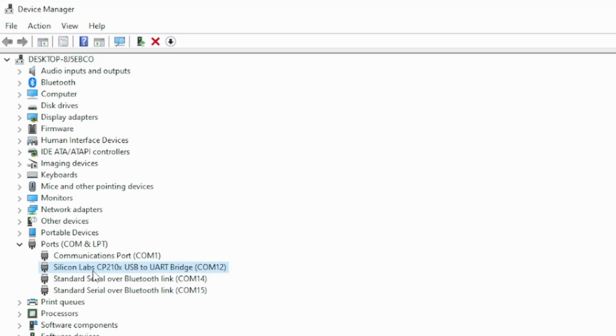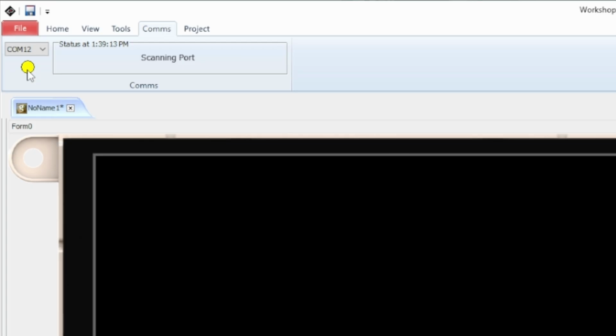If the connection is successful, the indicator light will turn yellow briefly while it establishes the link, and then blue once it's connected. If it stays red, double check your cable, your drivers, and make sure you've selected the correct COM port. If the display is detected but the PmmC driver or version appears in red text, that means that it's outdated. That's what we're about to fix.